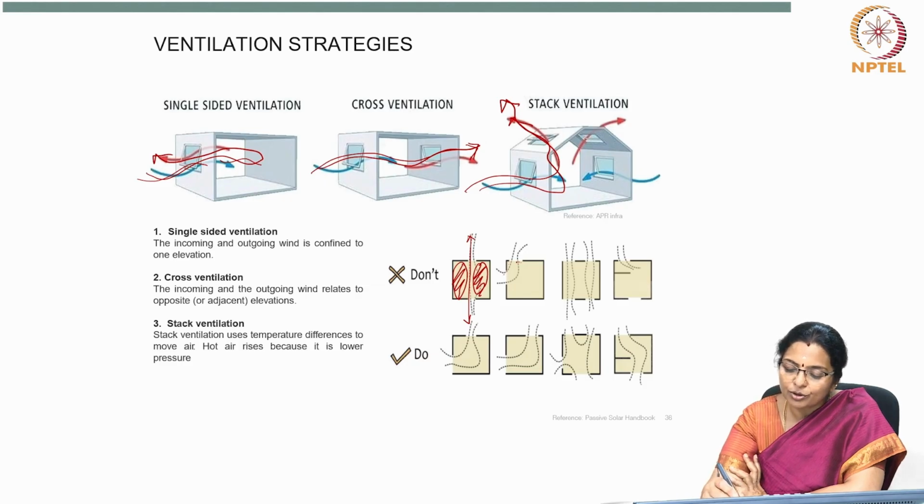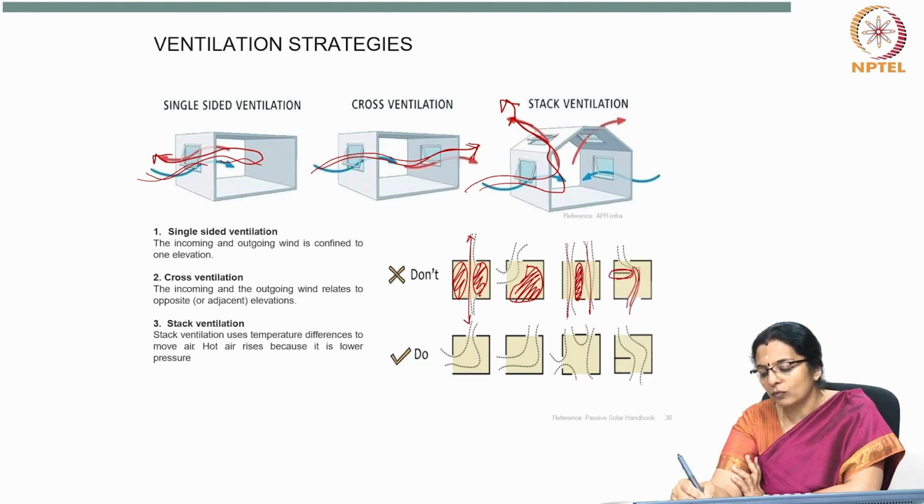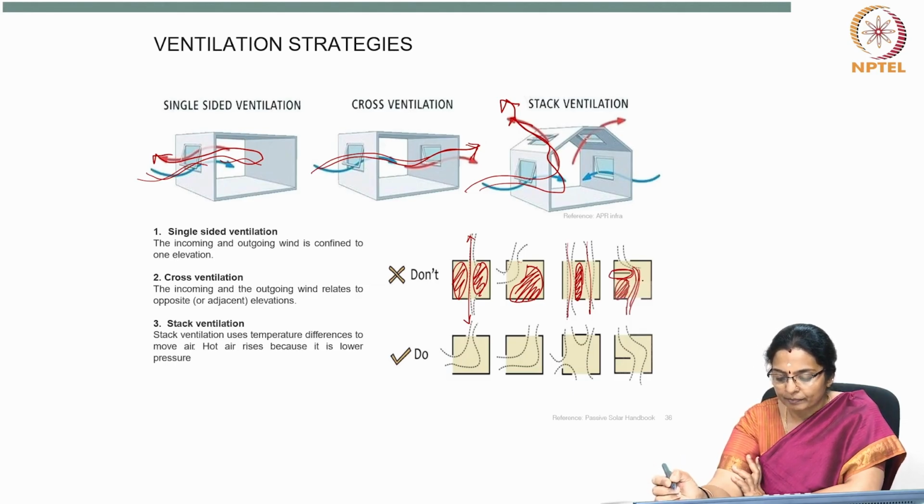The apertures should not be next to each other, as a large part of the room falls under wind shadow region. You must also not have openings parallel like this, as the center part is wind shadow region, and you should not have walls like this, as they function like wing walls to divert the breeze, causing wind shadow region.